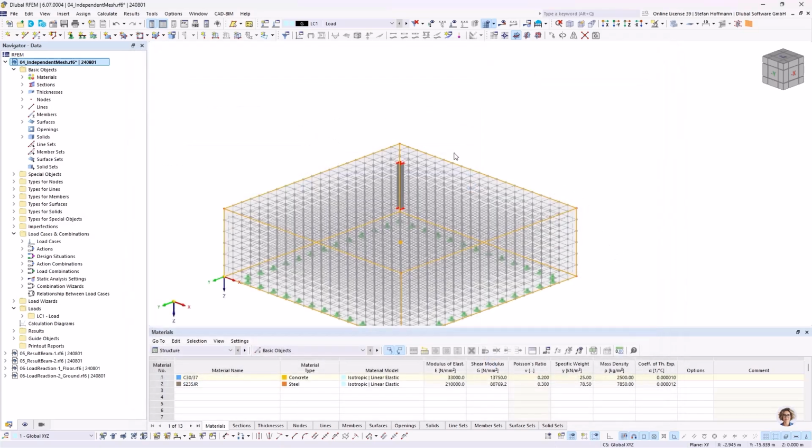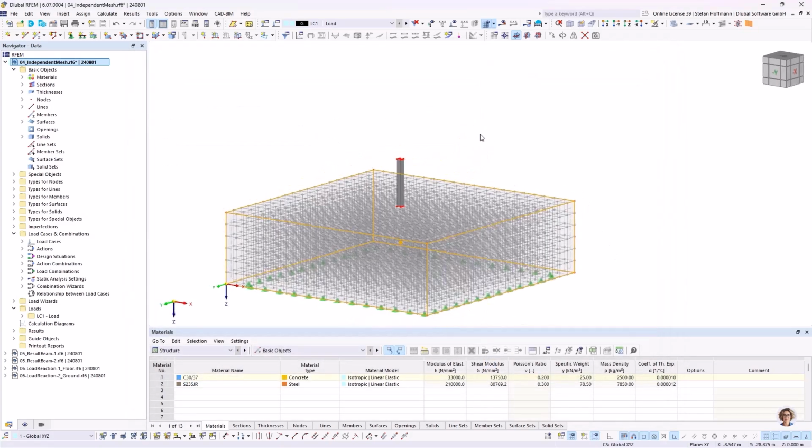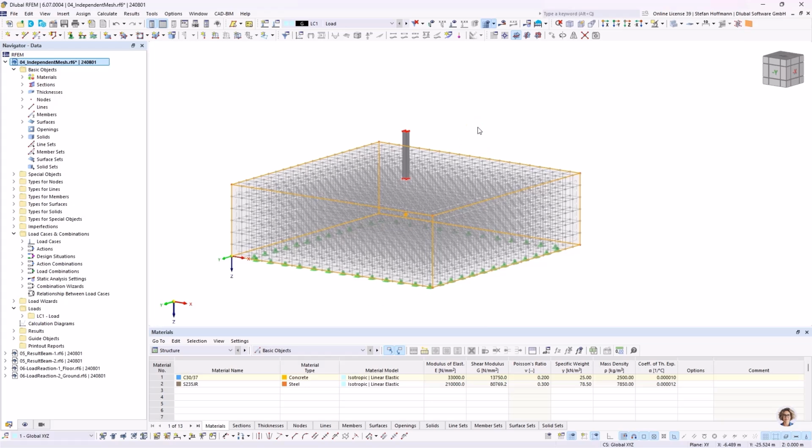So these settings will most likely allow you to have a better optimized mesh and shorter calculation times. And of course the forces and the objects will still be connected with some settings in the solver and distribute the forces into the connected objects, but now without the need of the same mesh. Okay, let's go to the next example.